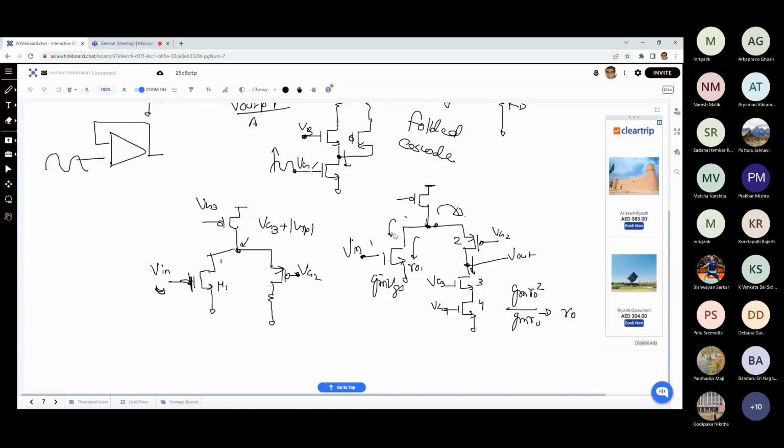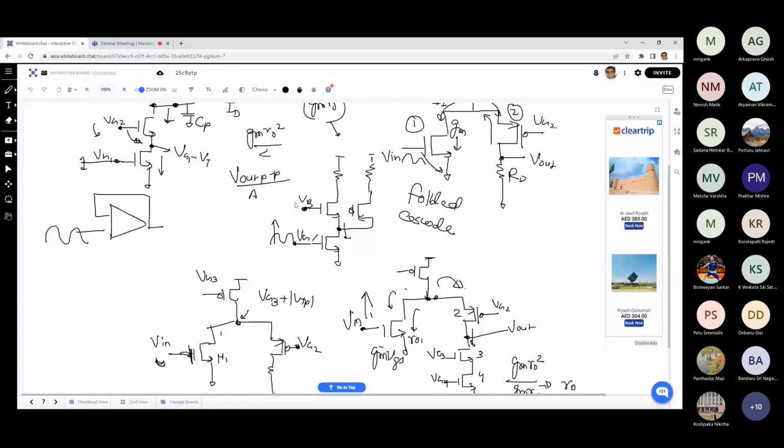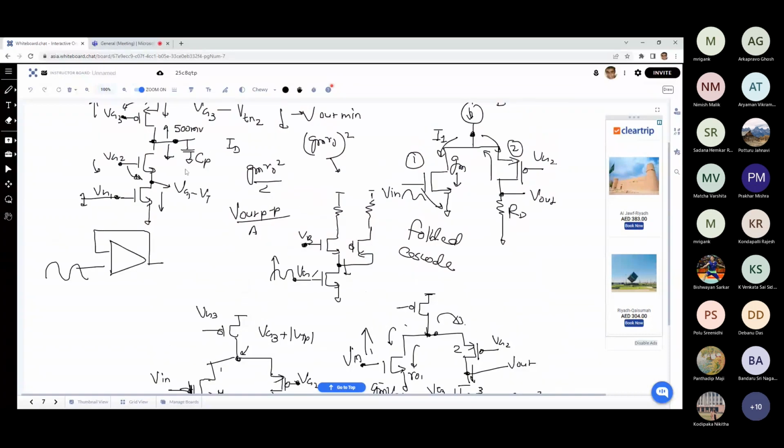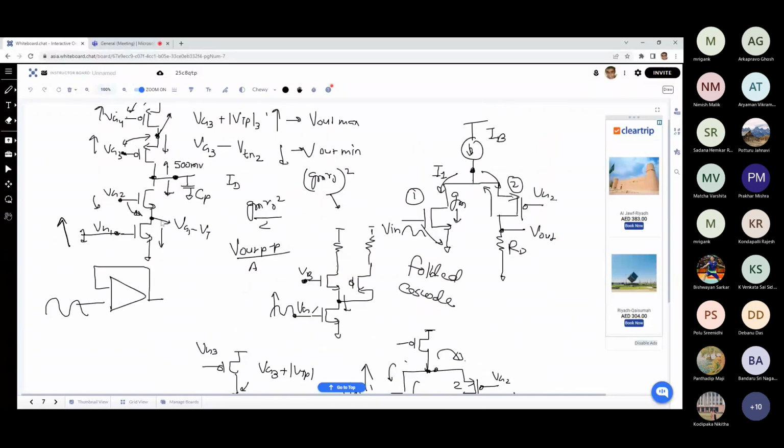And on the upper side, if you are increasing the input voltage, earlier there was a direct conflict between the input swing and output swing. So here, if I increase the input voltage, my output swing consideration has forced me to lower the drain voltage over here, right? So I am trying to push it to the lowest possible value so that I can maximize the swing.